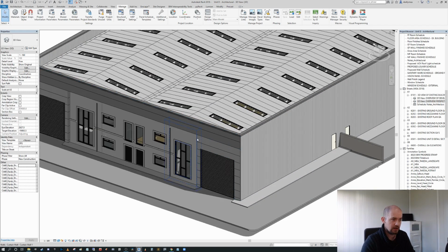You can merely highlight one element of the chain. So let's say this middle wall. And I can press tab, you may have to press it several times, but you will actually get the selection. So you can see chain of walls or lines actually comes up as the selection criteria.